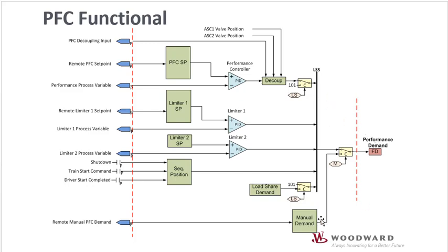A manual positioning ramp allows a user to set the final demand at a desired level. This can be used for troubleshooting or when bringing different controllers into and out of control. Tracking logic allows the mode, so whether you're running in auto mode or PID control versus manual mode, where the manual demand ramp has control, tracking allows you to switch bumplessly between these two controllers.